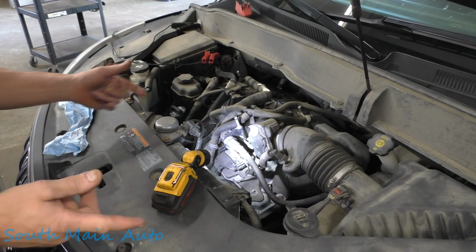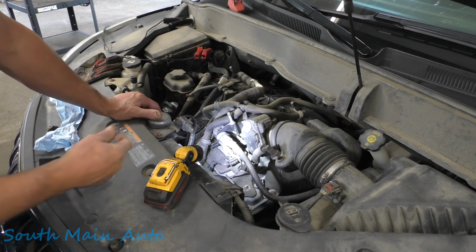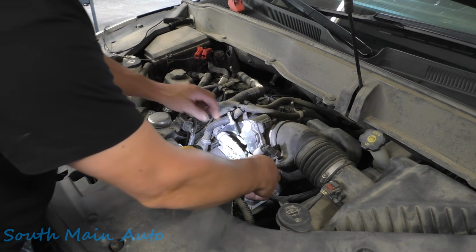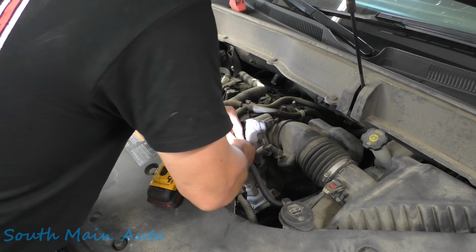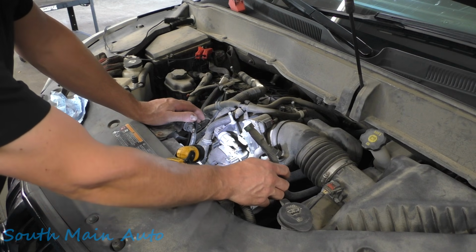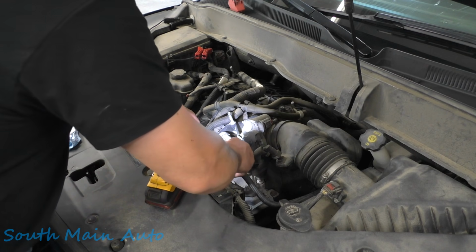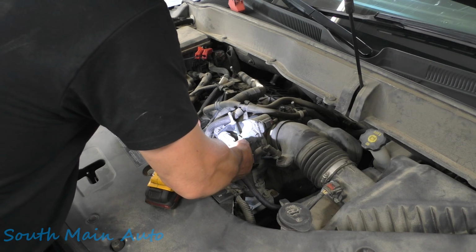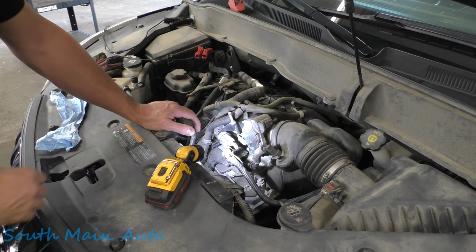The reason I check it like that, A, it's easier, and B, sometimes you touch these suckers and they start working miraculously. So we're gonna try to just squeeze the tabs here, unplug it. So this is the vapor line. Oops, that might have just made it start working. Usually you whack them with a screwdriver, they'll work in. This is the vapor line that runs to the tank. And then to make sure it's not stuck electrically, we just simply unplug it. But sometimes that's all it takes, and then they'll start working again.